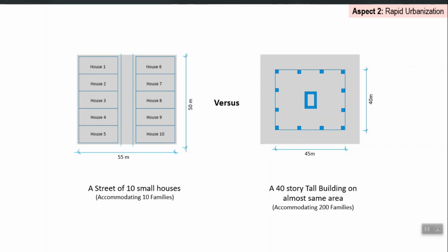So, the general process goes like this: you first start with conventional code based design. You follow, for example, ACI, ASCE 7 or IBC, and then you come up with one design. Now, the conventional structural engineer will just finalize that design. This will go to the drawings section and go to the field, but performance based design will be explicitly checking that design's performance. So, actually that final design which the conventional structural engineer will finalize will become an initial design for PBD.